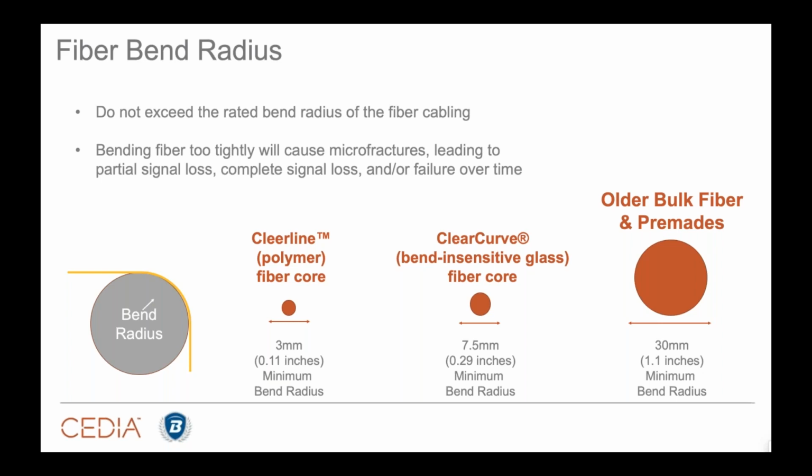But here's the catch. If you're going into a retrofit, you may not be so lucky. There may be fiber optic cabling that's been installed and it does not feature this bend-insensitive glass or these polymers. You've got to be careful. And part of it is you don't want to get glass shards in your clothing, on your skin. It's an irritant, but more importantly, you want to make sure you don't damage that installation.